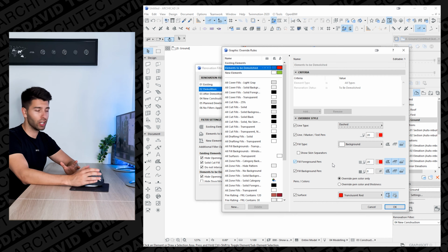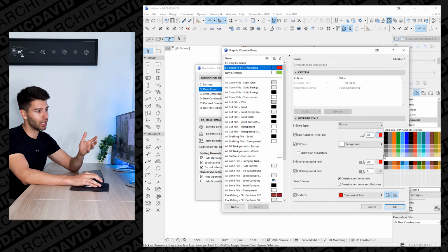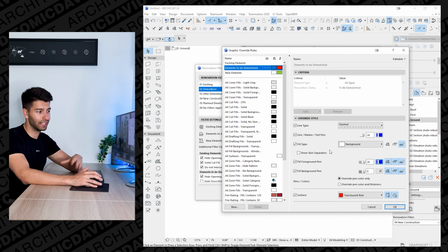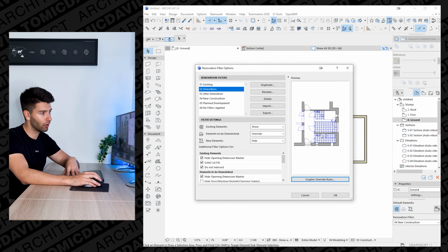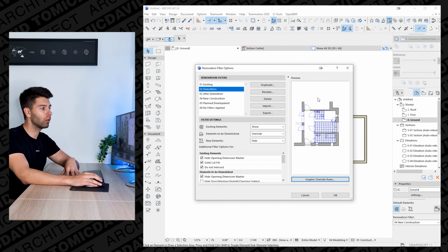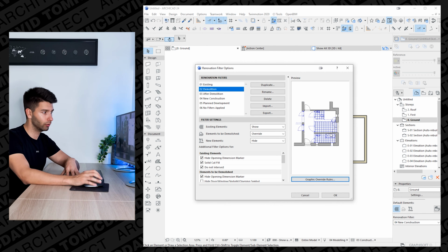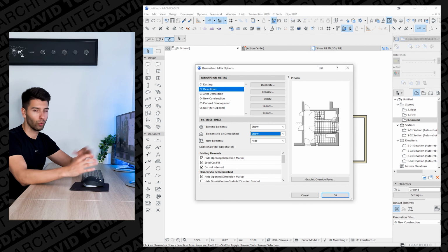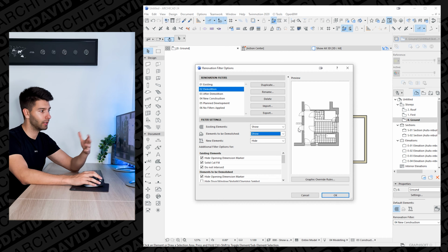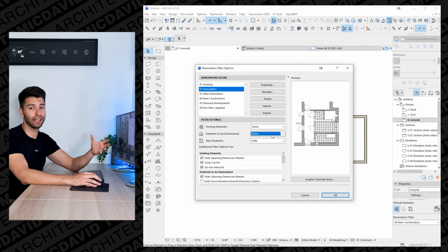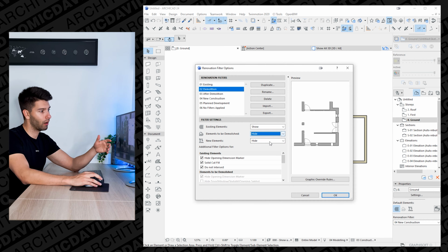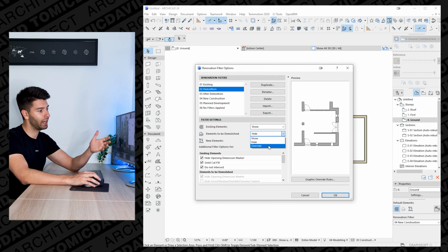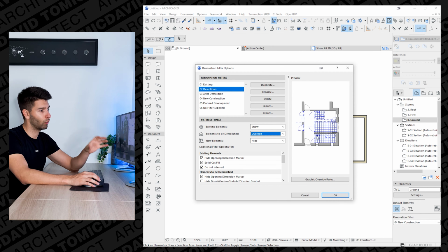knock it out. The same way we changed that orange on the existing layer, we can come in here and change it to blue, for instance, if, for example, blue is the accepted color in your country, and just click OK. And again, we'll see all of those elements change to blue. Now, if we went back into our filter settings and went show, we would see them just as if they appeared normally. There'd be nothing gone, and a demolition layer would kind of become redundant. If we went hide, again, it would become redundant because we have our after demolition layer, but then our override rules really get us where we need to be.